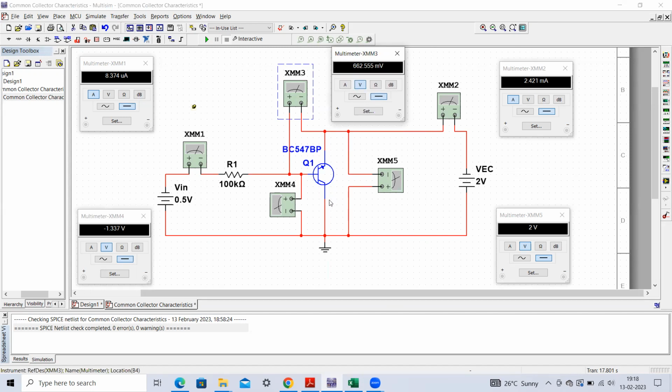Basically, because it is an NPN transistor, this terminal is N type, this is P type material, and this is again N type material. So here you can see that this makes a PN junction, fine, the base emitter junction. So whenever this base emitter terminal is forward biased, this transistor will be in the conducting state, that you have to remember. And you must be aware that for silicon transistors, this base to emitter voltage drop should be around 0.6 to 0.7 volts, because it corresponds to its cut-in voltage, fine.